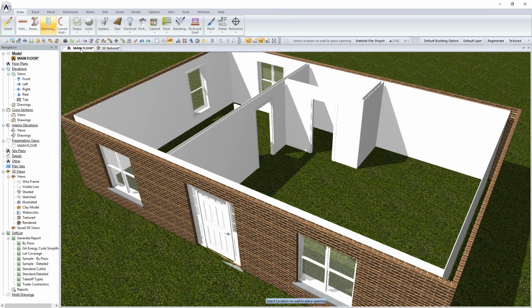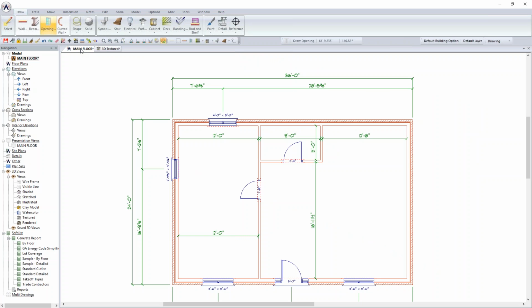Okay, so there is a lot more to SoftPlan, obviously, that you would do. There's going to be things like editing of openings, etc. But the key to this is just learning some of the early fundamentals to get you started. Keep in mind, you can go to draw and select anything from the ribbon bar, but you can also right-click and pull up this item right here, to get you into that menu quickly. Keep in mind that most of these functions have a shortcut. The S would be draw select, and you'll be able to quickly get to a menu item by hitting that on the keyboard.